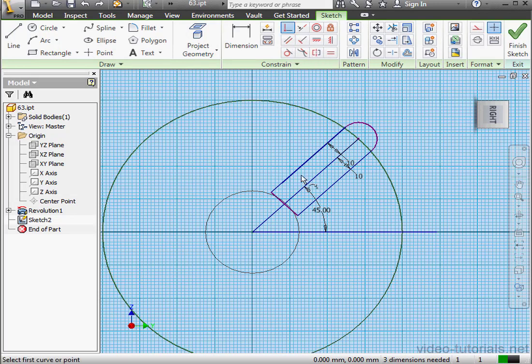Let's take a moment to apply some constraints. I'll select this point and this point. Let's apply an equal constraint to this line and this line. One more dimension is needed, says the status bar, so let's also use an equal constraint between these two lines. And press Escape to exit the Constraint tool. Let's convert this line to construction geometry. And this line as well. Oops, we need the bottom segment. And let's finish the sketch.